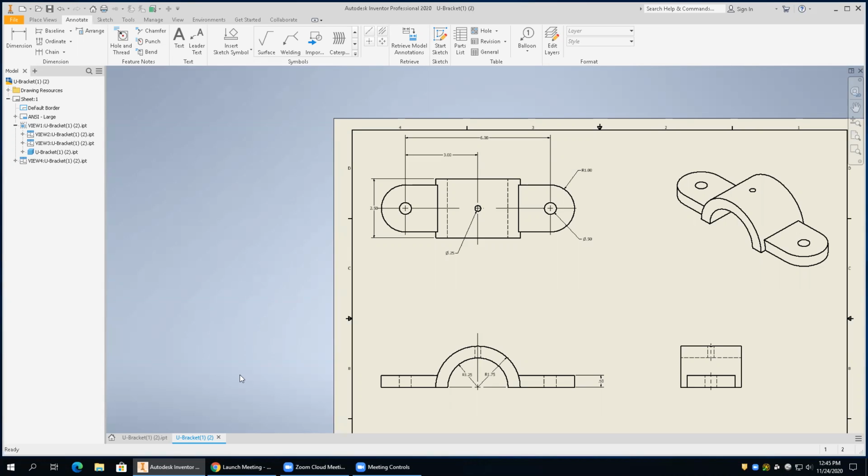So there's some other things. You can do 3-dimensional dimensioning and that kind of stuff. So if you want to read a little bit more about that in your book, you can do that. On the drawings we're going to be doing, that's the base level stuff you're going to need to know how to do. Throw some dimensions down on it, put some bisector lines, put some center marks. Okay. So in this next set of drawings, that's what you're going to be doing. The one thing,